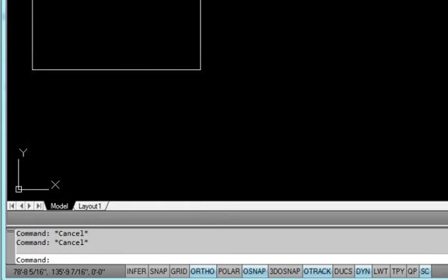Okay, what you'll need to have picked are Ortho, OSNAP, OTRAC, and DYN, which stands for Dynamic Input. You'll know that they're selected when they look illuminated or a light blue color. When they're toggled off, in other words, when they're turned off, they'll be a gray color.